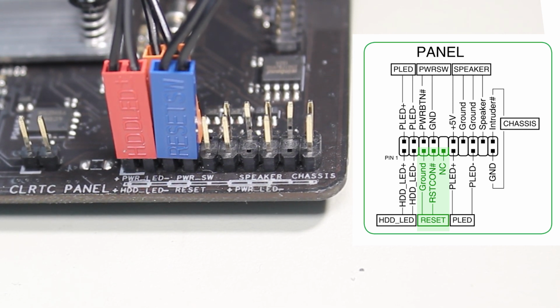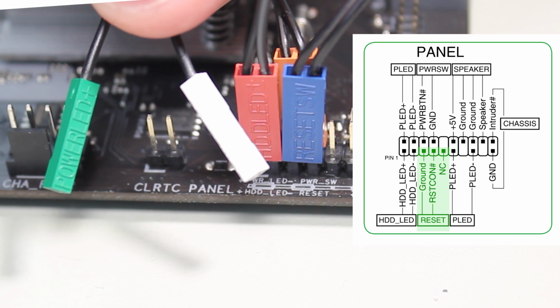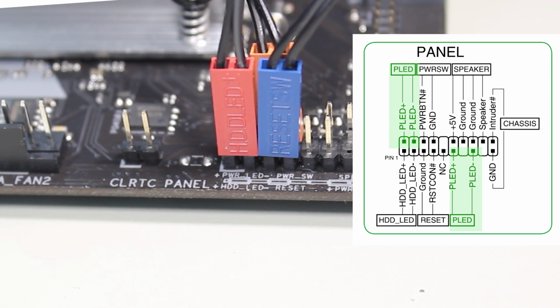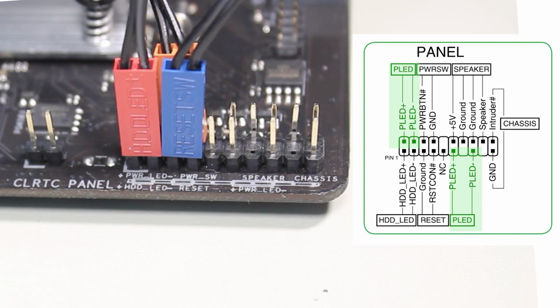The next one is an interesting one. It is the power LED. It is interesting because it is split into single connectors. The reason for this is that you can see that there is a 2 and a 3 pin connector on the motherboard. The history behind this is that some motherboard manufacturers use 2 pins and others 3 pins for the power LED. To accommodate which is being used, the computer case manufacturers split the pins into single pins so they could be used in a 2 or 3 pin connector.